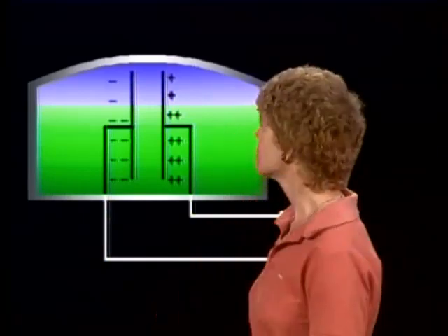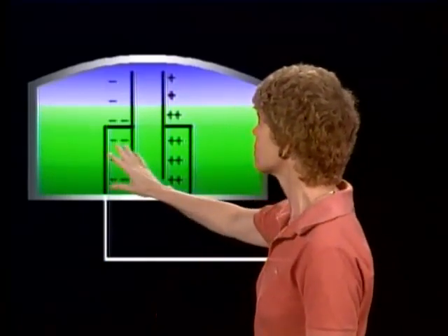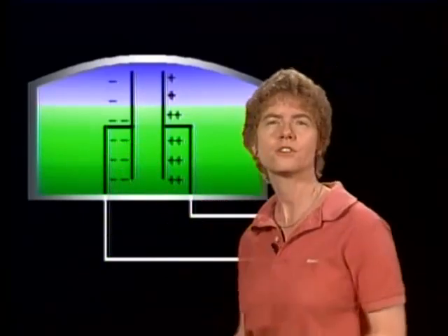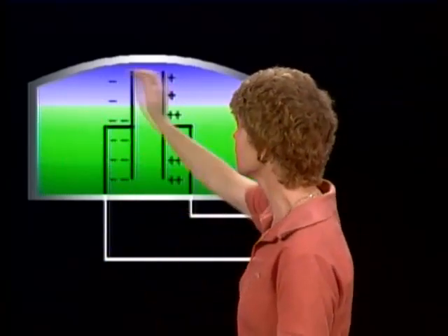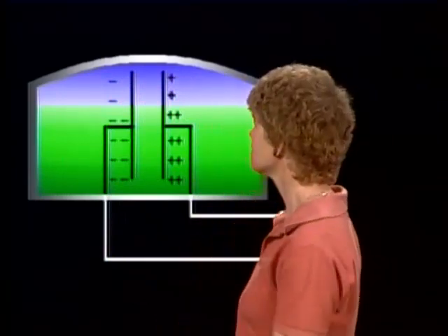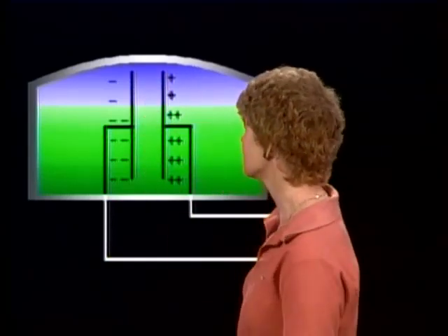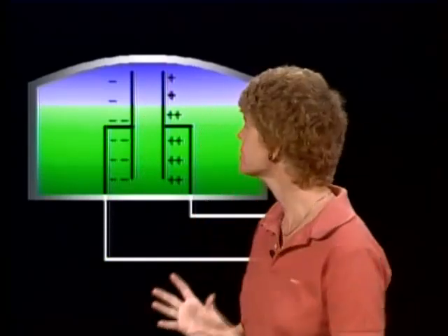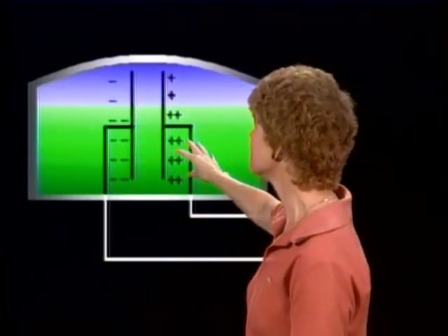So basically what you've got is charges trying to move from one side of the electric condenser, which is the probe, to the other. But you have the fuel and you have the air, which are the dielectric, the non-conducting material, between the 2 parts of the probe or the condenser. What happens is that the non-conductivity of the fuel and the air is different.